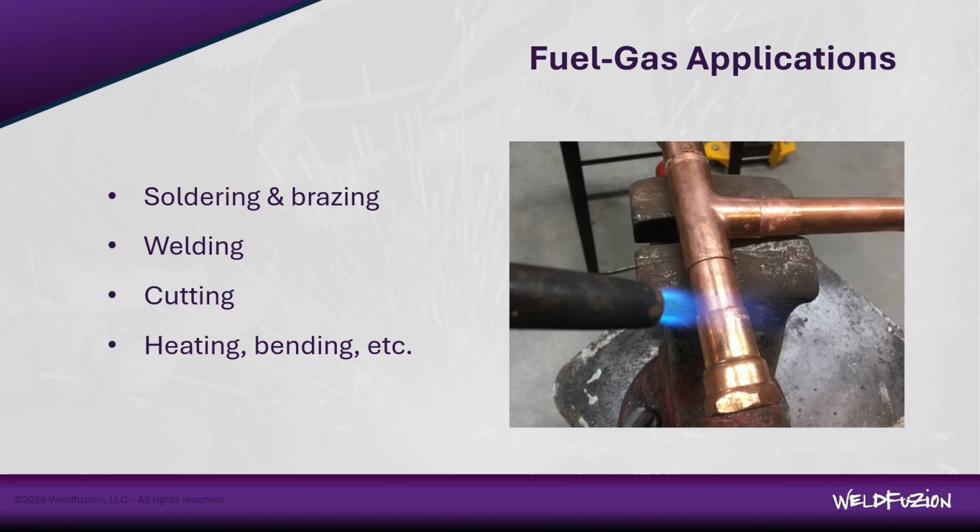In terms of productivity, oxy-fuel welding consists of slow travel speeds and low deposition rates in terms of pounds per hour. So while it was capable of welding on the first automobile assembly lines, it couldn't possibly keep up with today's automotive manufacturing pace. The process is often used for cutting, but limited to steel, and it's very capable of repairs that require soldering or brazing. And I say repairs because production soldering and brazing wouldn't normally employ oxy-fuel anymore either. Not that it's not done, but soldering and brazing are done in ovens with arc or laser processes today.